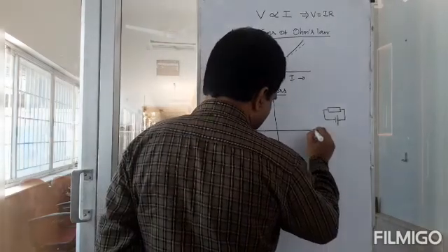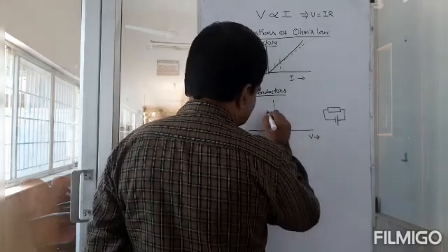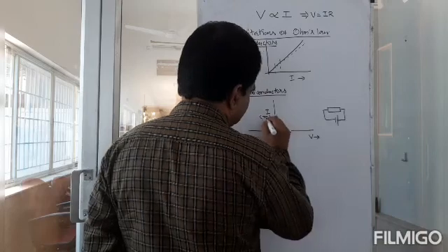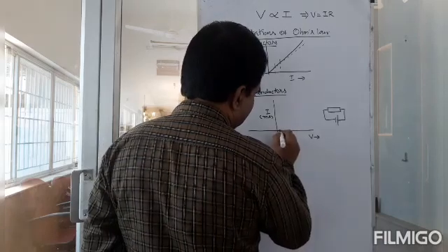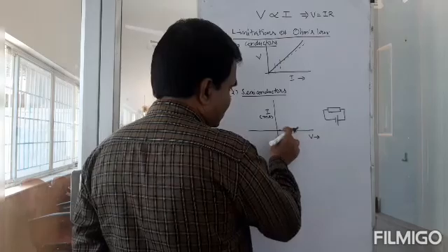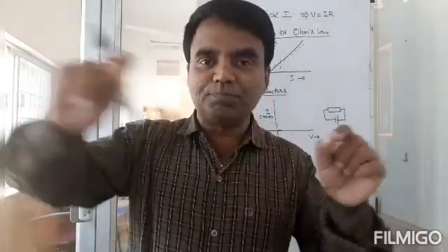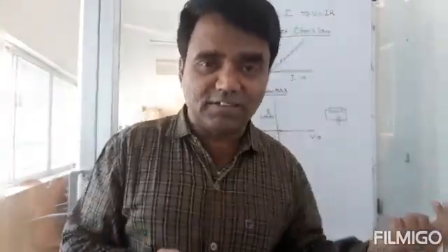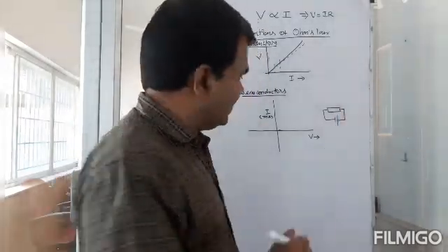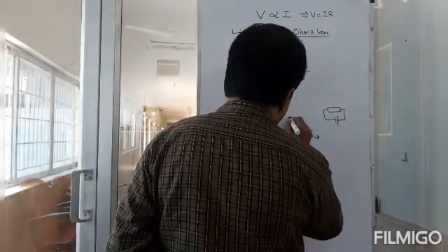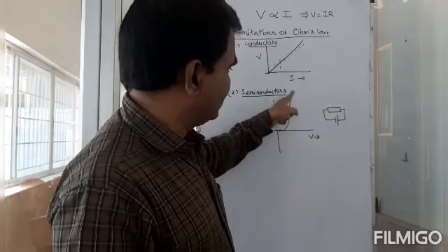In the forward bias condition, I keep increasing the voltage, and the current is going to be in milliamperes. If it is a silicon diode or something, the current won't start for a certain amount of voltage, till 0.7. Suppose you are varying the voltage from 0 to some value. At 0.1 you won't get any current, at 0.2 you won't get any current, and 0.7 is the voltage at which it starts conducting. Then current suddenly increases. You don't see Ohm's law being obeyed in this range.